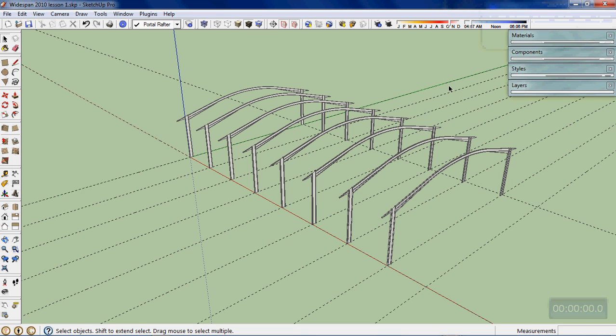Okay, now that we've got the portal frame set out along all the grid lines, I'm going to start to set up some of the fascia facade elements on this building. We'll start with some concrete tilt-up panels, and I'm going to alternate some concrete tilt-up panels. They'll be 3.6 meters high, and they'll go alternately between separate portal column bays. So we'll close off this section through here, and we'll close off this section through here.